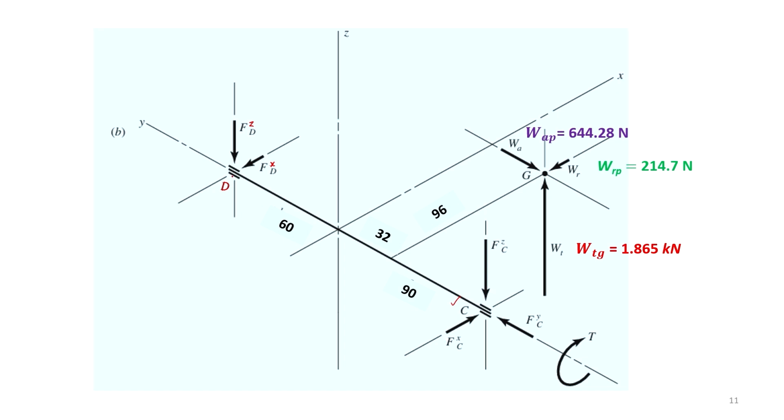On the D bearing, reactions only in the directions of x and z are taken. Along the y, which is the axial direction of the gear, is not taken, because this will not take the axial load or the thrust load. Thrust load will be taken by C.